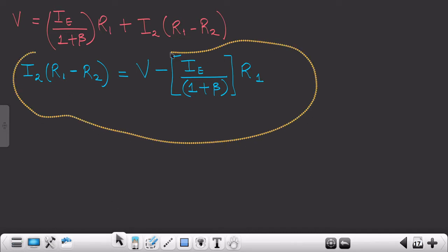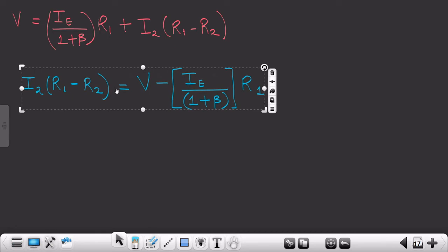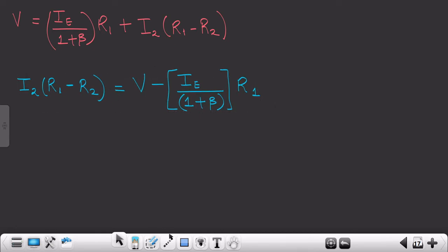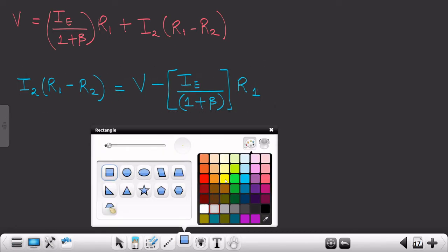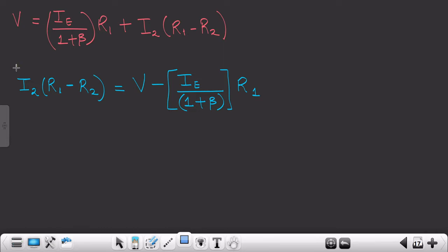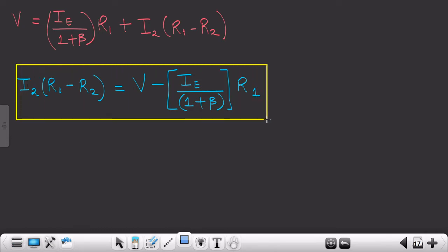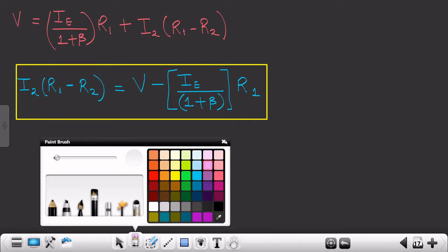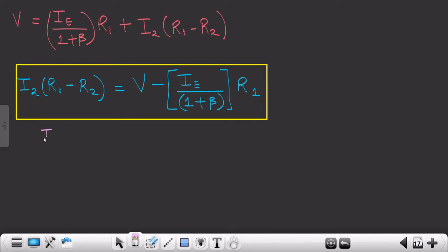With the help of this equation, we can easily say that voltage divider bias is also a self bias circuit. Now you will ask me, sir, how come? Like, I'm not able to understand anything with the help of this equation. See over here, we all know that IC is almost equivalent to IE, right? So if IC increases, that means your IE also increases, right?